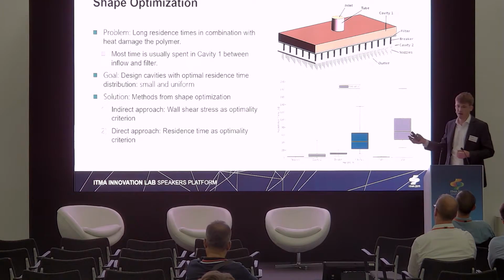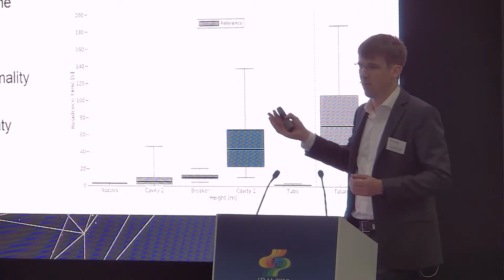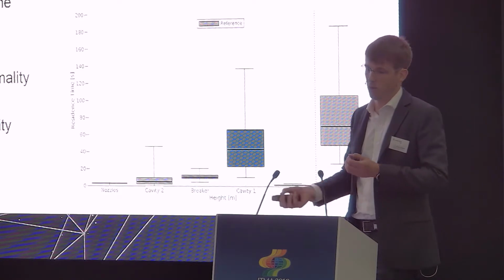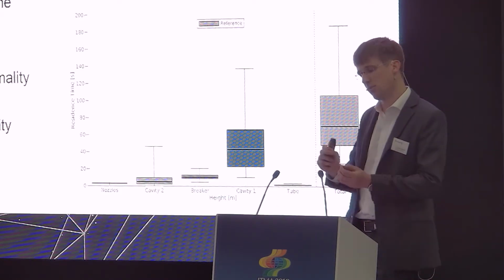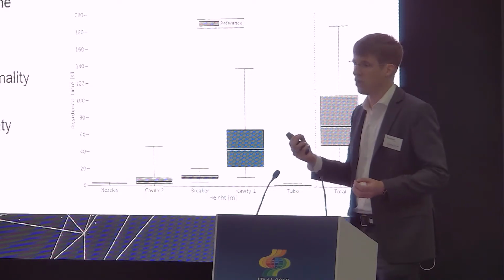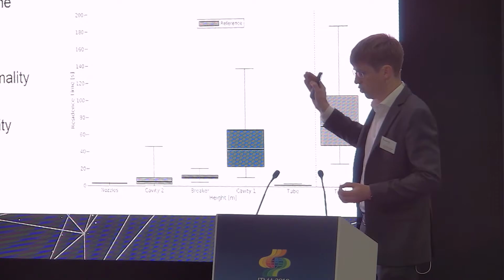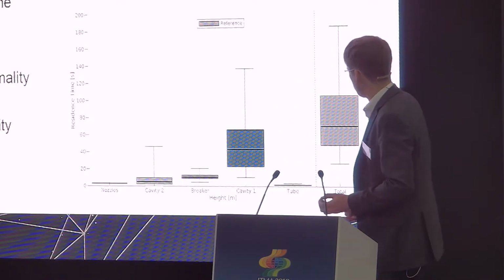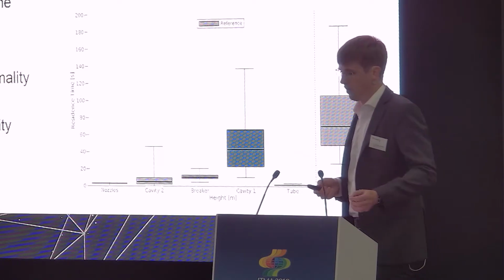So especially if we are talking about bicomponent spin packs with very small channels, then you would probably get a totally different picture, because then suddenly pressure plays an important role, and you will see the regions or the small channels where the large pressure drops are generated. But just for this showcase, we now have a look at residence time, and we want to reduce the residence time of this cavity.